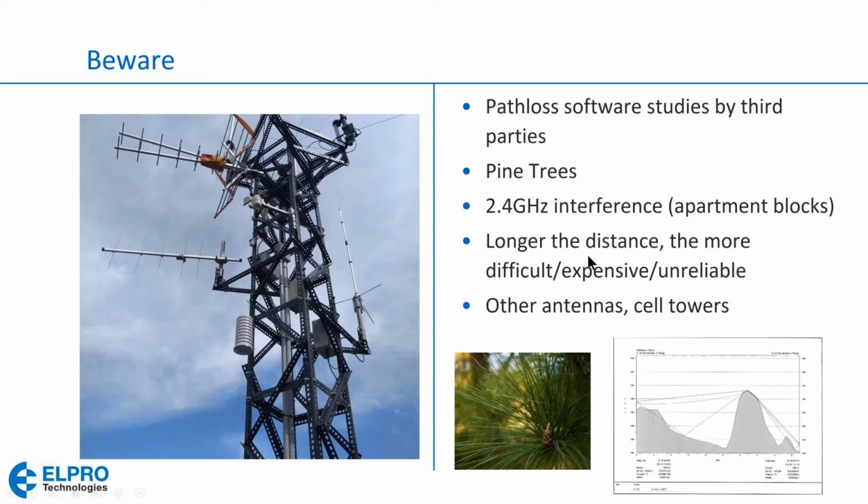Also just be aware, the longer the distance, the more difficult it is because you have to have equipment to be able to climb up and mount the radios up higher. The more expensive it is because the taller the tower, the more it's going to cost. We need higher gain antennas, we need longer runs of coax, etc.